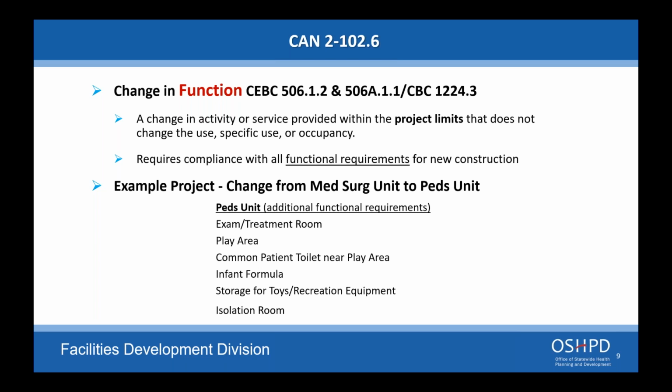A lot of the questions we get are about the pre-balance report before you do that. You know, if you have an HVAC unit that's not running, what do you do? You can't balance the air because there's no air coming out of it. And what you have are a couple options. If you have the original design drawings for that, you can balance it to the original design levels.